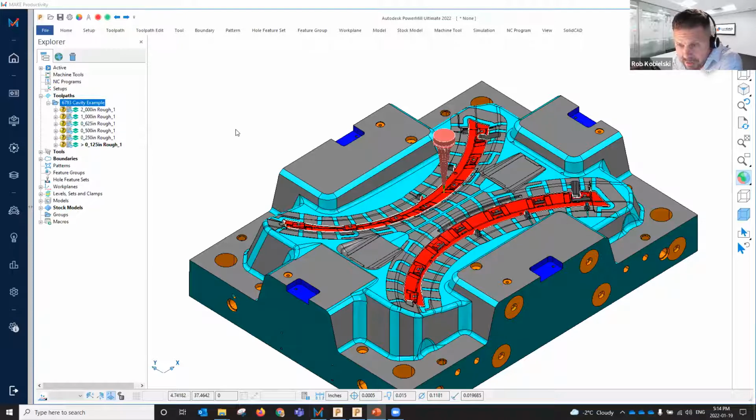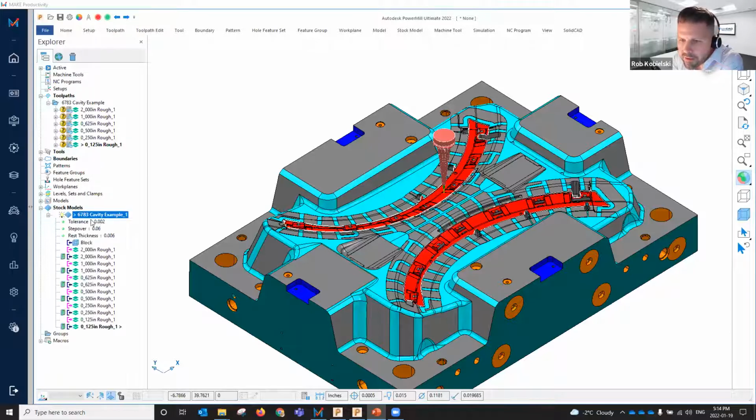It's only 6 toolpaths because, as I said, it's roughing and semi-finishing only. But the important piece is the boundary elements were all applied to this. The specific tools I went through were all applied to this. And most importantly, all the stock handling has been applied to this. So all the stock model references and states, to ensure that when I calculate this toolpath, we're getting an optimized result to minimize all that air time. Okay, so this was the basic process, and it is as quick as that. You can expedite it if you wish to work with dedicated tools, or leave it flexible as such.